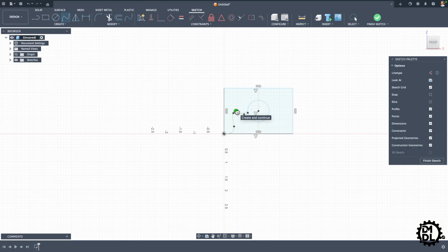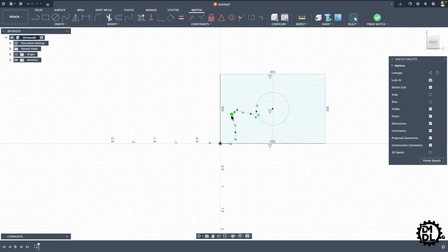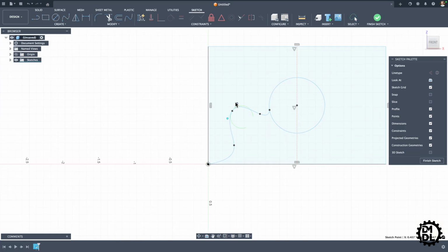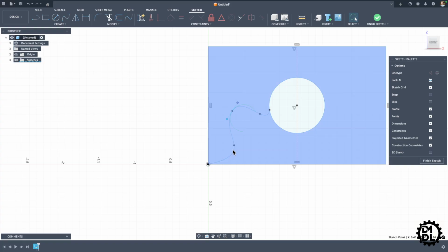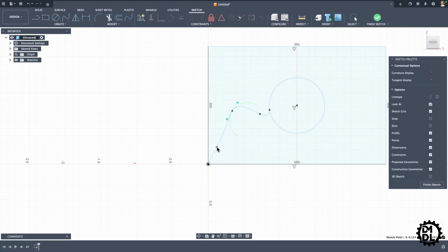And here, click the check mark, and that spline is created. And now we can grab on and we can adjust this. So it's essentially a line with some curvature to it that allows you to get a bit more wavy or some curvature to your sketch if that is something you want.